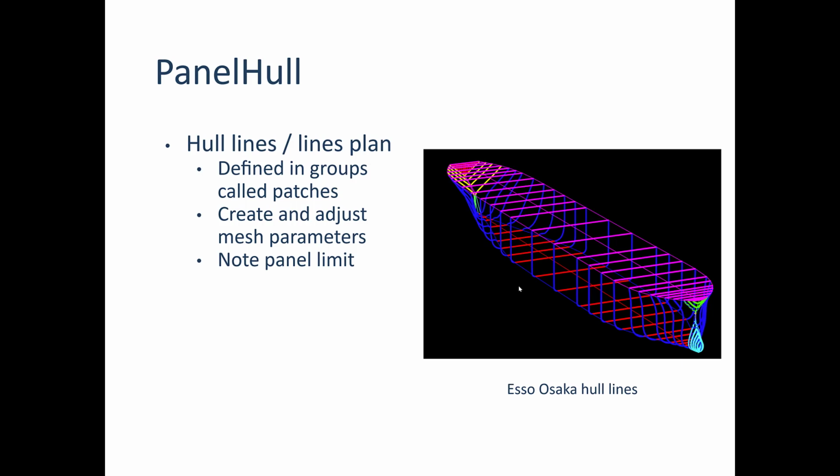Then you get into the first application, panel hull, and this is all about generating the hydrodynamic mesh that's required for calculating wave excitation forces: those incident loads, diffraction loads, and wave radiation loads.